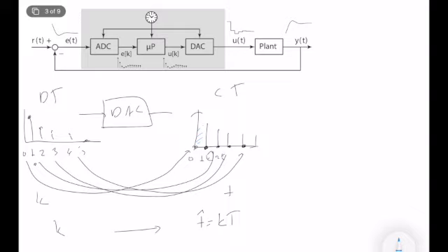Okay, so the most useful, dominantly used digital controller uses the concept of zero order hold. What is zero order hold? Is this. Okay, so you read the value of the discrete time signal at 0, and you keep it constant until you hit the next sample. Okay, now I have the next sample. Sorry for that. It should be 0. So let's clean this. Okay, this is like this. So this is 0. Now I have the next sample. This is like this. Now it is like this. It goes like this.